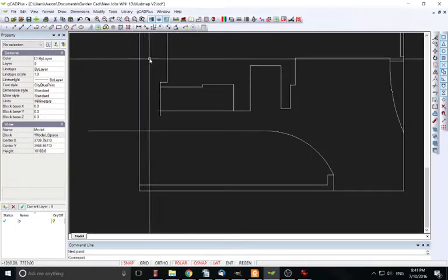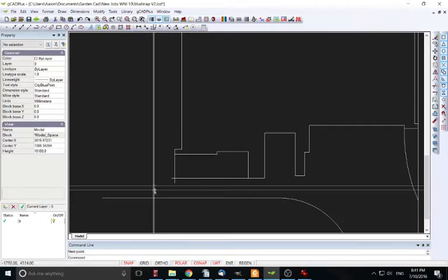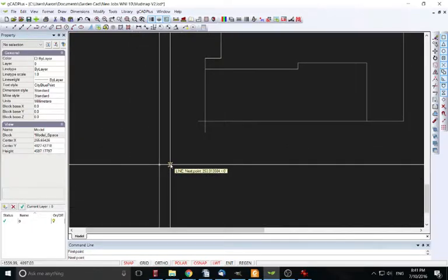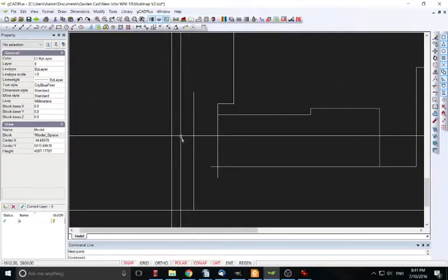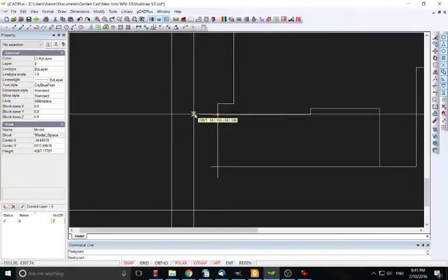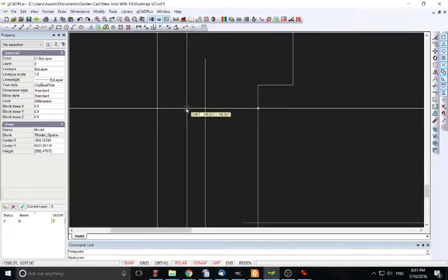So what you might do is just draw a line, and so we can fit a little garden bed in. So we're there, 500, and then we went this way. So if we had a 500 garden bed against that fence there, you can see how narrow this walkway is. Tools, distance, it's 500 essentially, so it's just way too small. You're really going to need a gate about 800 or 900. So at this point you're essentially just making that a whole thing gate, because it's the only access to the sideway of the house. I'd probably rather, in my own house, have that wider, so that's probably what I'm going to end up doing.